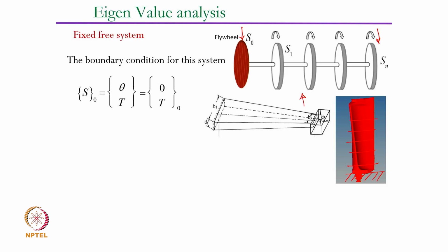Can we say that the flywheel being so heavy, we can treat that end condition to be a fixed end condition? We have seen that in vibratory system modeling, a simplifying assumption could be that if the inertia of the flywheel is large enough, we can treat it as almost rigid. If that is the case, the twist there will be 0, right? But the torsional dynamics of the entire gear train is going to generate the twisting moment at the root,